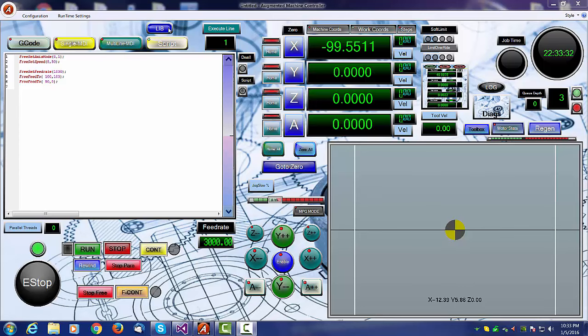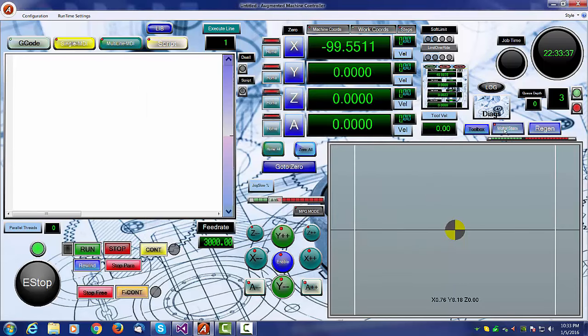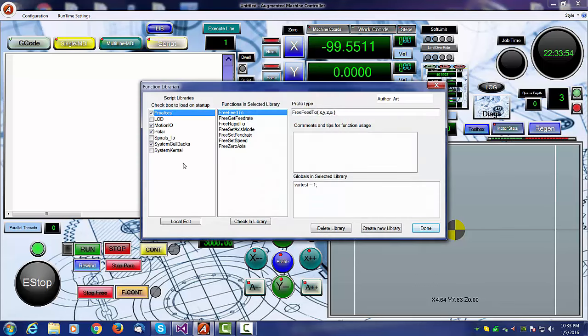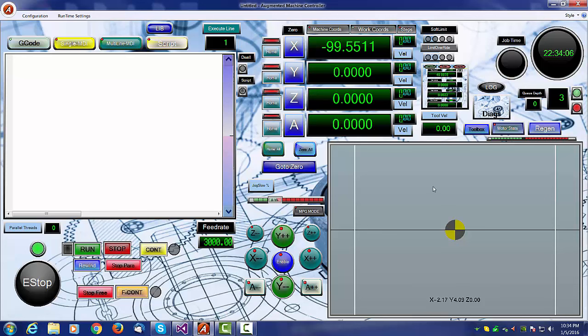It then loads our libraries from the library selections, and then after that it loads the screen interface scripts that you find in the scripter for the screen. It is this order that you want to consider fairly important, because since the libraries load first, they cannot see screen interface objects. So you should not put routines inside libraries that try to talk to the screen, because they'll often fail during their initialization, because the screen is not yet created. This is just one of those chicken or egg problems that you'll always run into.